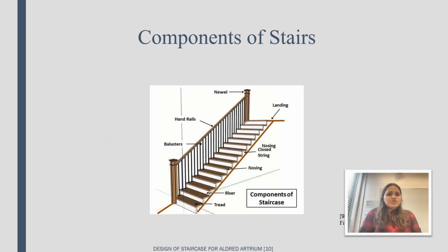As we all know, the tread is one of the most visible parts of the staircase structure, horizontally placed above the risers, where we physically put our feet. Risers are the elevations provided between consecutive stairs. To support the treads in position, stringer beams are provided laterally beneath every flight, whereas support beams are provided below every landing to support its connection with every level.